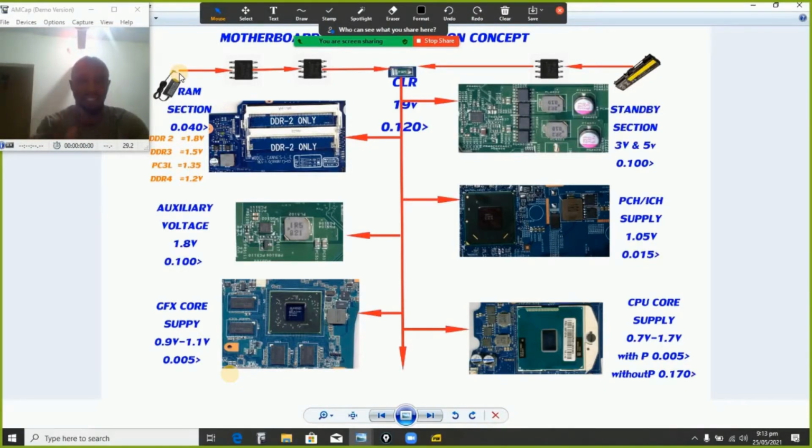So where is the final destination? We are talking about the LVDS. That is where the screen connector is. That is the final destination of the voltage. If there is a voltage that has to do with display, and you are checking LVDS, that doesn't necessarily mean we'll catch our faults at that LVDS point, because we need to confirm whether everything has worked perfectly before checking LVDS.